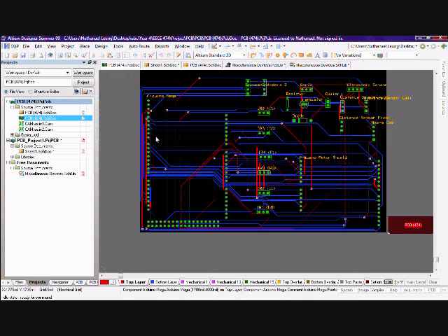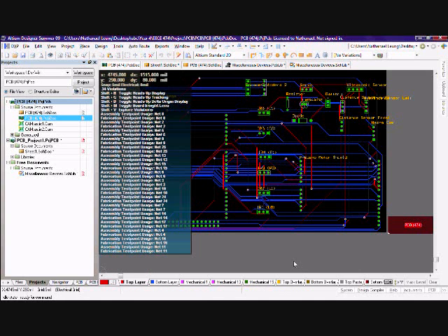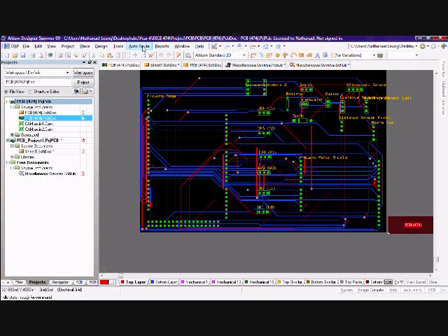That being said, all the routing is not done. They are not organized, and everything will be overlapped. In order to make sure that all of these are routed correctly, you will click Auto Route, click All. In this screen, you will route all. After that, this will all route.